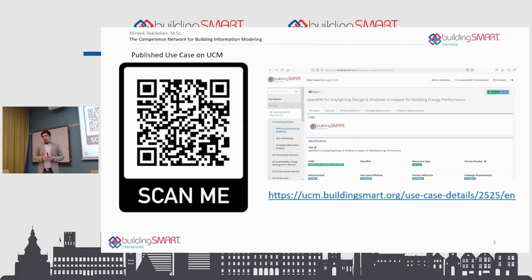export IFC. But the lack of implementation of the BSDD API makes it difficult. You need to use custom properties. You have to bring them to families, in Revit it is a family, and especially if you don't have a database with material building parts, you need to create those families yourself. Even like the chair, if I know I have a certificate for this chair and I know the specs, I create a simple geometry, I check the dimensions, so that's like a dimension that I need to fill in, especially for MEP parts.